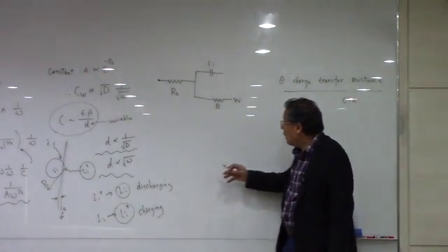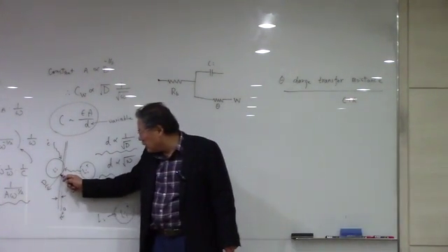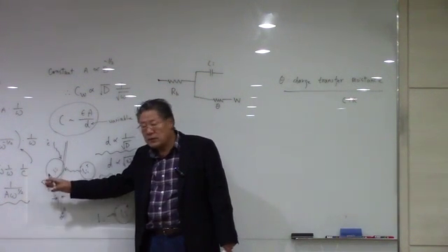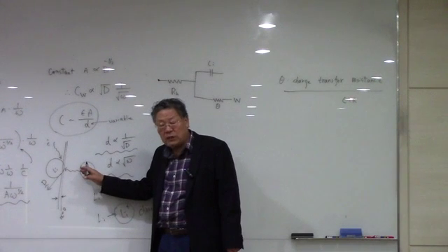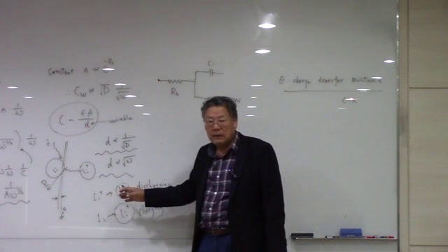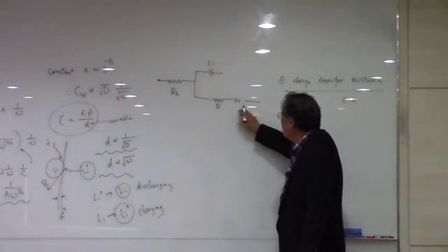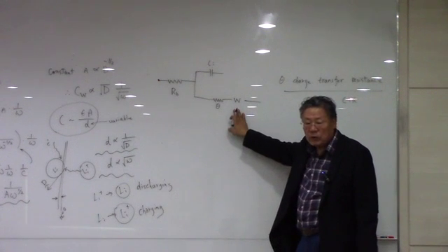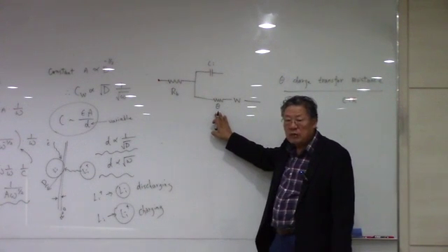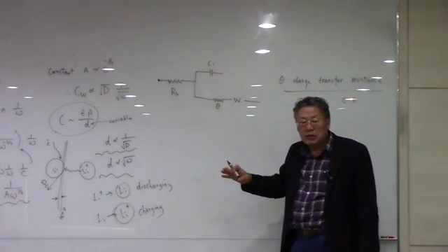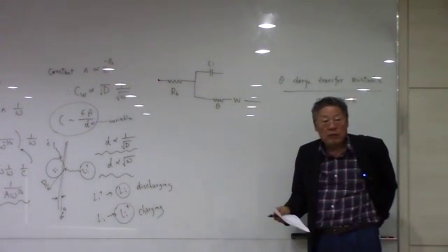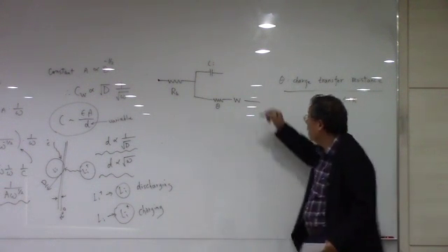Okay? And that is related to how fast the lithium is going to be diffused out from the surface, or how fast the lithium can diffuse towards the surface where the reactions are in a charging process. So this Warburg is related to the diffusion coefficient of the reactive element, but this charge transfer resistance has nothing to do with the electroactive species diffusion coefficient, the diffusion phenomenon.